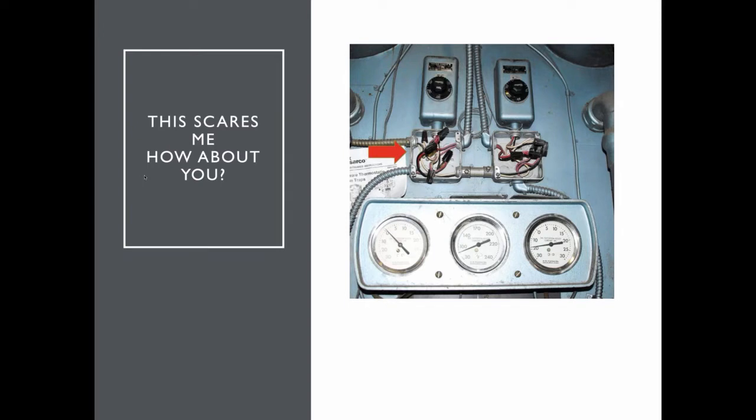I don't know about you, but this really scares me. When I walk into a boiler room and I see the 4x4 covers gone, it makes my spidey sense start to tingle. And I'm thinking, did they jump out the safety controls? What did they do? And the ASME CSD-1 even references this too, that they want these 4x4 covers put back on.